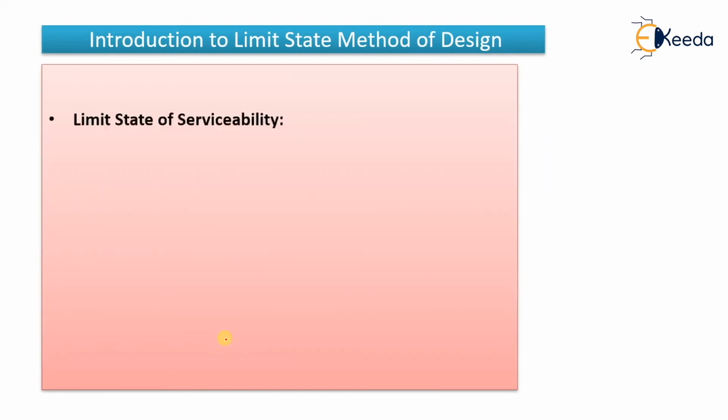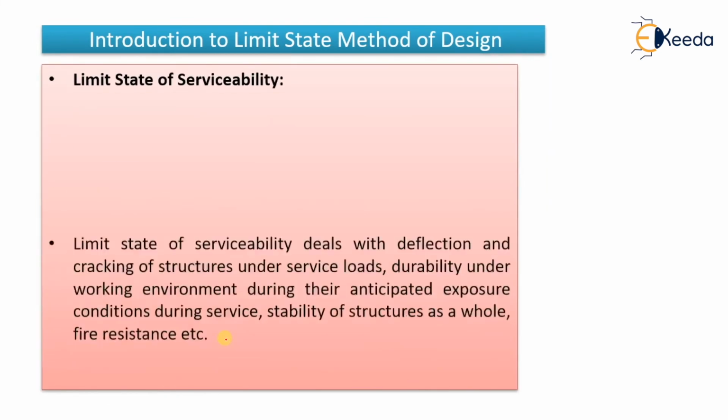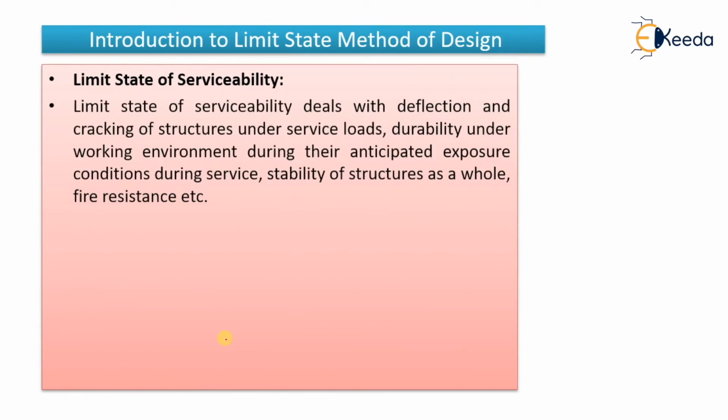Now, the second type, limit state of serviceability. What does it mean? The limit state of serviceability deals with deflection, cracking, and, as I told you, vibration of the structure under service loads, durability under working environments during their anticipated exposure conditions, stability of the structure as a whole, and fire resistance.